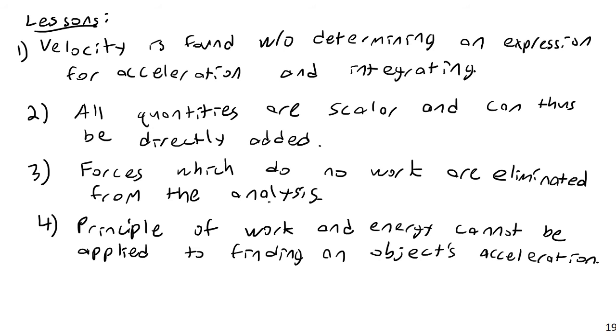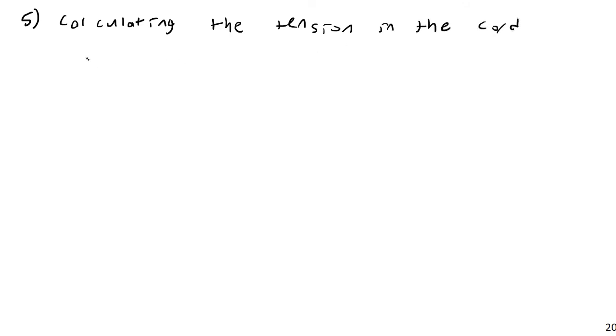Let's see. Other things. More takeaways of this. If I wanted to calculate force in here, I couldn't use just the work energy formula. Calculating the tension in the cord, we would have to consider forces in the cord. That requires supplementing work energy with Newton's second law.